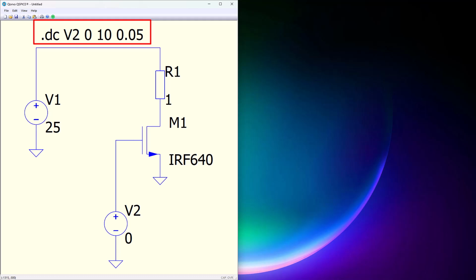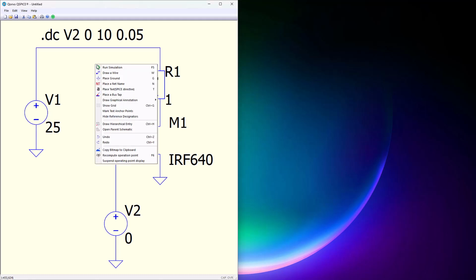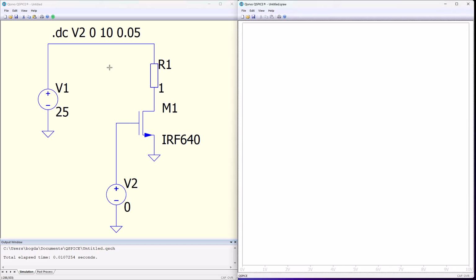So what are we actually doing here? We are asking the transistor a single question, over and over again for each value of VGS. How much current will you let through? And the answer, on the vertical axis, is the drain current. The 1 ohm resistor on the drain has only one purpose: to limit the maximum current to a reasonable value. Without it, the simulator would happily report more than 50 amps at VGS equals 10 volts, which is not physically realistic. We hit run and we get this curve.